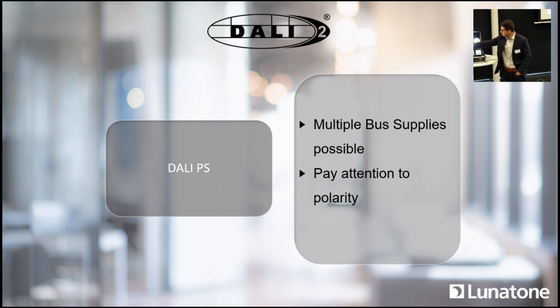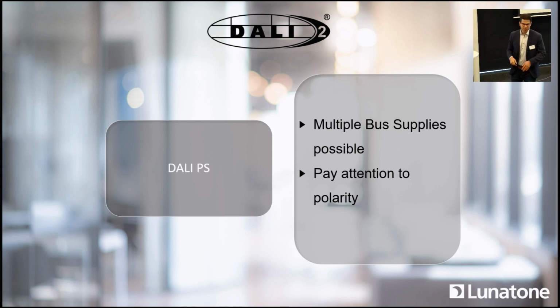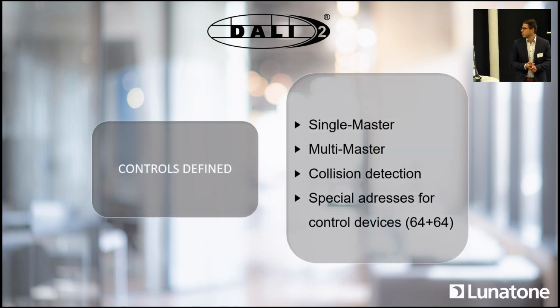So you can add another piece of this, and then it's 80 plus 80. But of course, if you want to do that, you have to pay attention to polarity. So minus needs to be connected to minus and plus to plus, because otherwise, big explosion. Probably not with 16 volts, but it won't work. That's the downside. They won't break, but it won't work. So just be careful about that.